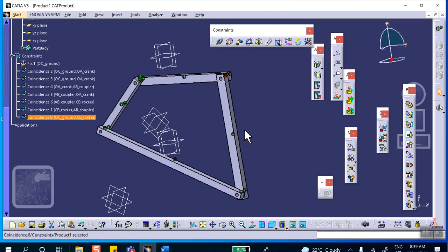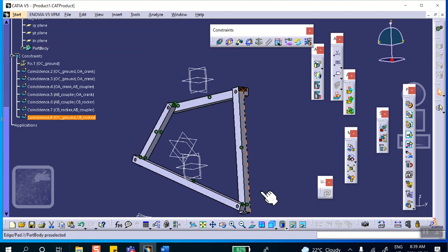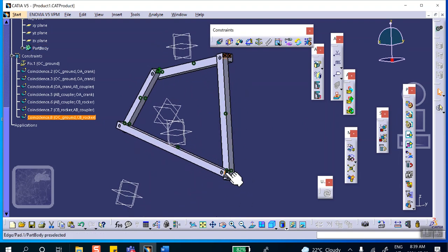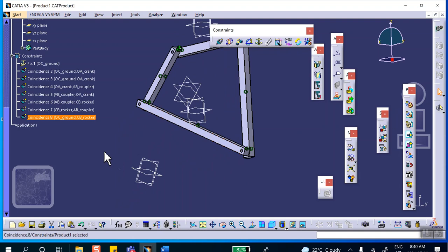There's only one thing, and that is, notice that it ends up in the right spot because I padded these the right amount. In other words, this bottom one is going to convert into a cylindrical joint. If you want, I can also do a face-to-face, and it's going to become revolute later on. But it is not necessary. So I should have 3 revolutes and 1 cylindrical the way it is. If you had done for the last one face-to-face, you would get 4 revolutes, which is unnecessary, but that's fine. So save everything.